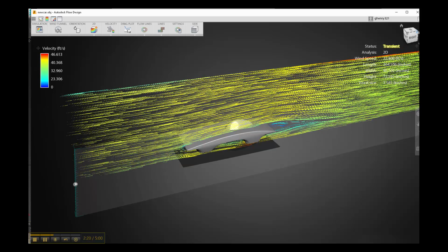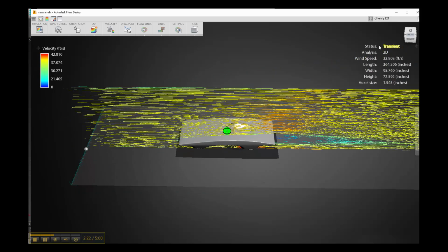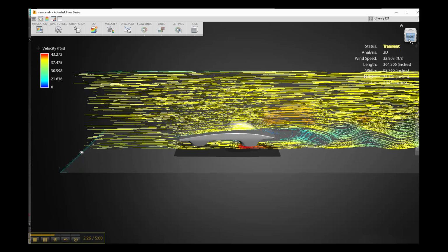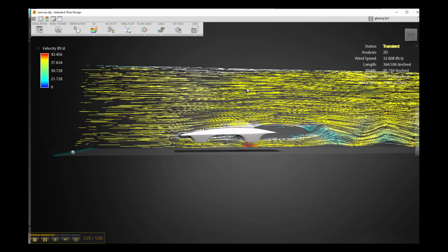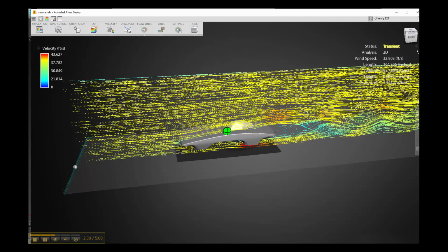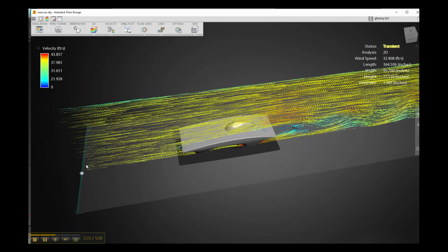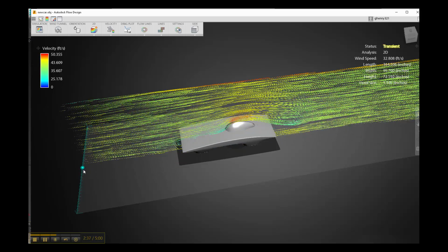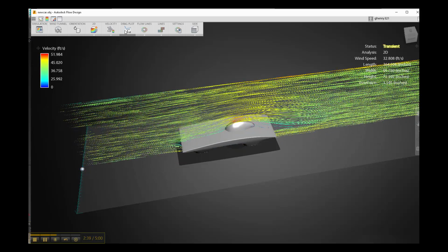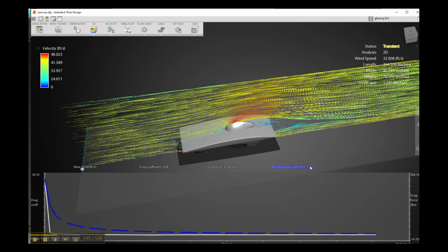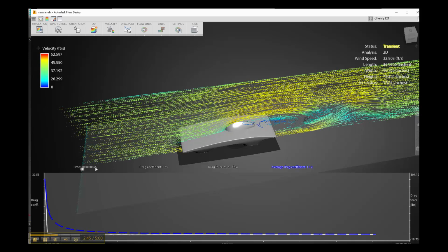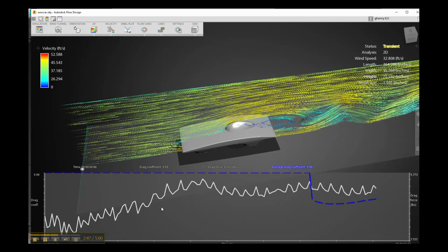See here, right? This is not cutting down the middle. This is cutting toward the side, so it's not hitting the canopy at all. So there's much less turbulent flow coming off the rear than there was a second ago when it had to go all the way over the whole canopy. And if you want to see the actual drag coefficient, you click this little thing that says drag plot, and you'll get drag coefficients, and you'll need time to elapse so it can get a better average.